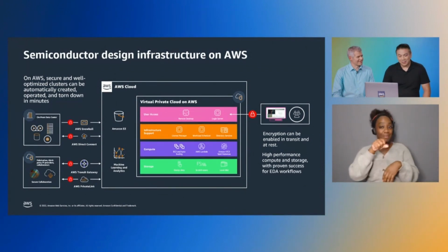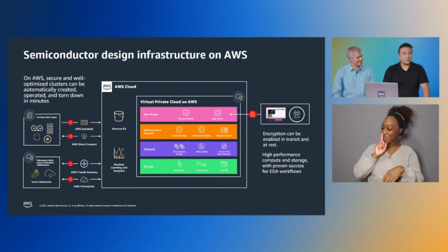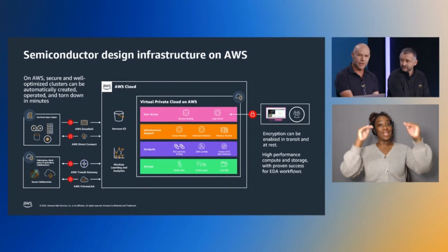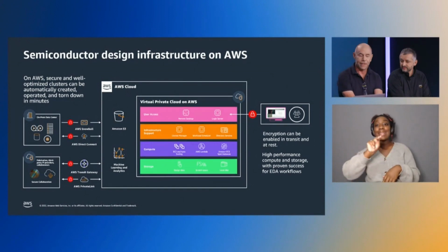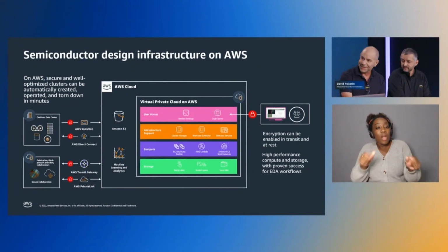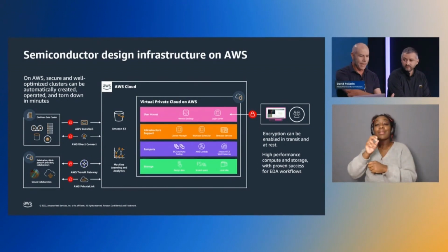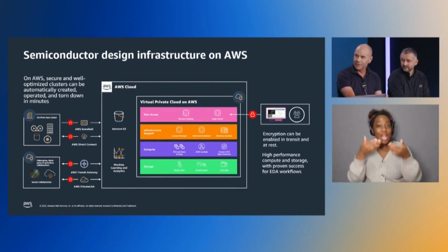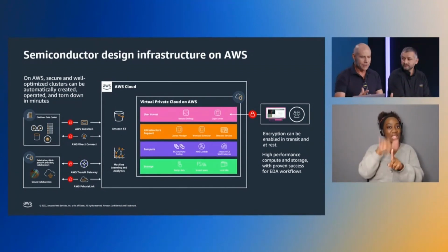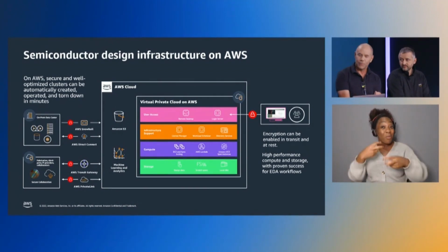Absolutely. So the challenge in manufacturing when you're at advanced nodes, 7 nanometer, 5 nanometer, and soon below that, is you're trying to use a lithography process, shining light through masks to expose the surface and create that chip. The problem is our geometries are now so small that they're smaller than a wavelength of light.